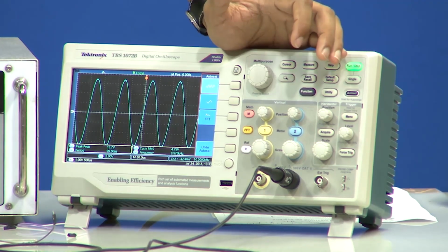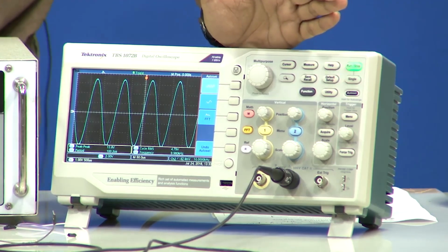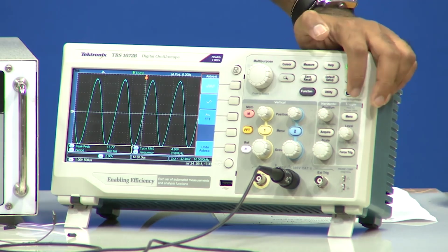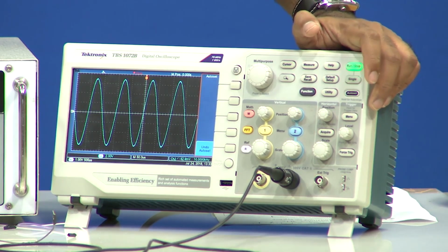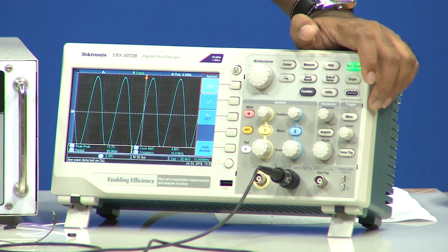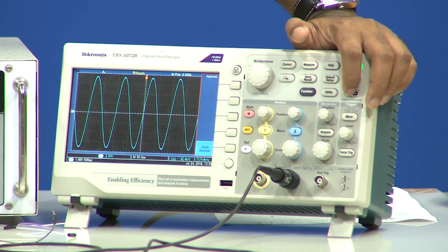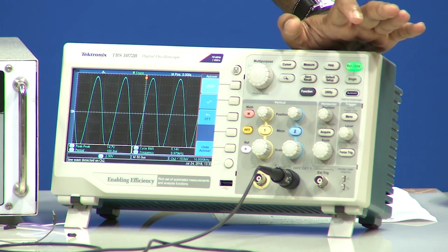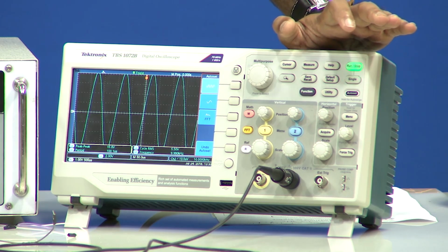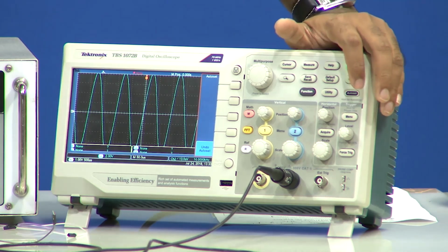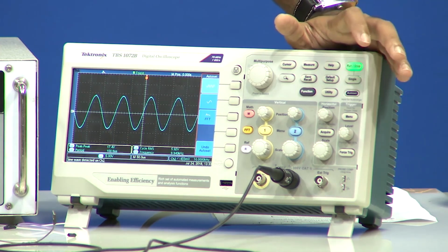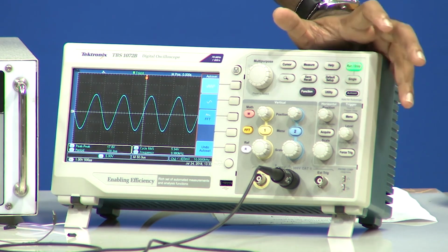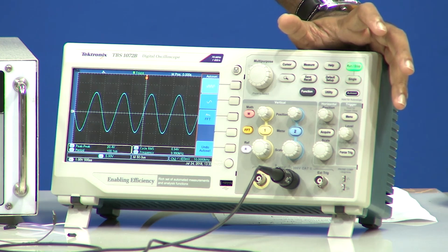Now it is 13.5 volt. Earlier, with 13.5 volt itself we were seeing saturation at the output. Now we do not see that, because the gain is unity, so you have more range at your input. Now it is 14.5 volt, and the output waveform is still beautifully sinusoidal without any saturation. 15.5 volt, 16.5 volt, and you are getting 17.4 volt. So, almost unity gain. See, it is following nicely.